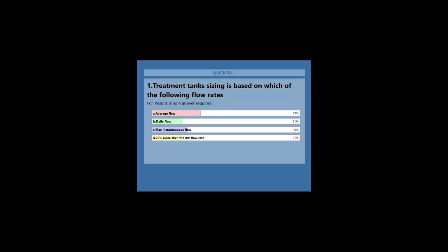While you could potentially oversize your system as a case for future expansion, that's not typically the norm with these style systems. And again, solving for your average flow rate is difficult because, as we look at a flow profile, you could end up with a flow of say 100 GPM for 10 minutes and then no flow for an hour, and you're going to come up with an average flow rate of say 10 gallons a minute, which is obviously just not the case.